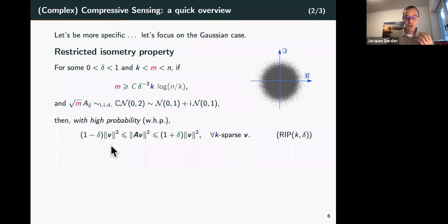And it happens that if you generate such a matrix randomly, for instance, with a complex Gaussian sensing model, which is represented in that formula up to a normalization, then you have exactly what you wanted from the beginning. That is the fact that this matrix will be RIP, provided that M is bigger than something that grows like the dimension of your model, which is here the number of non-zero coefficients you have in V, that is the sparsity level K. So provided that M is bigger than that, up to other factors that are here, you can show that with very high probability for any K-sparse vector V, this RIP property will hold. So that's the principle of this RIP property, which is good news because it means that if M is smaller than N, but a few multiples of K, you can hope to reconstruct your signal.